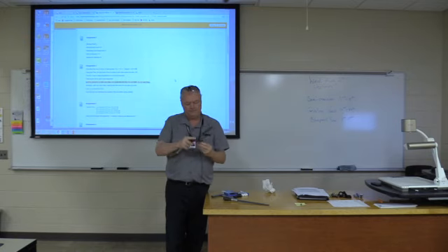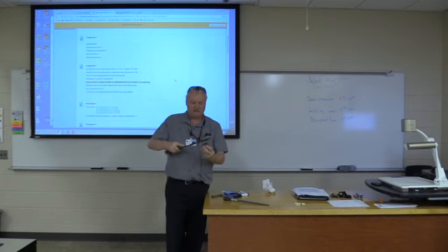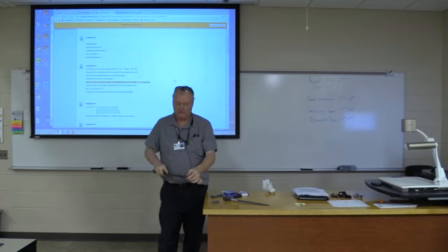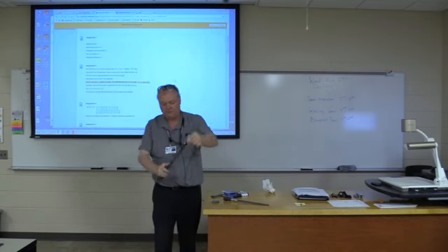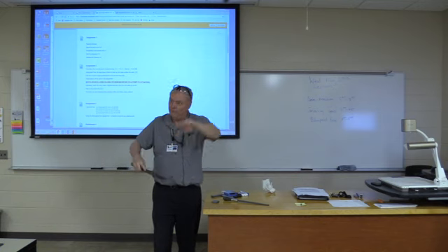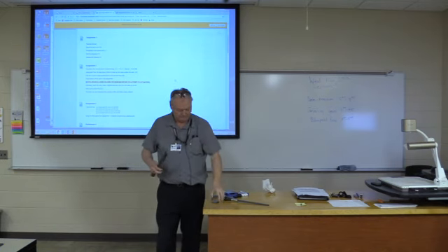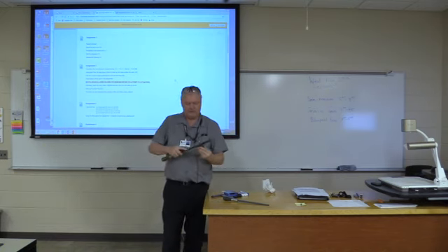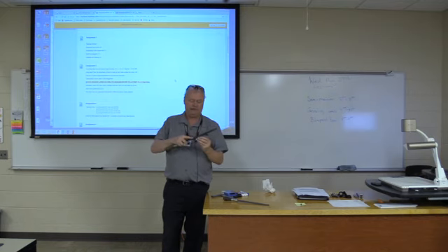But you'll see, you're not going to be scraping it like that. It's really just like saw cutting. Longer strokes are better. And what you want to do is those strokes have to be flat, because if you're stroking like this, you're going to round your part, over or under. So the assignment is to machine the two large flat faces, or file them rather, to within 5 thousandths. So whatever time it takes, you'll do that.